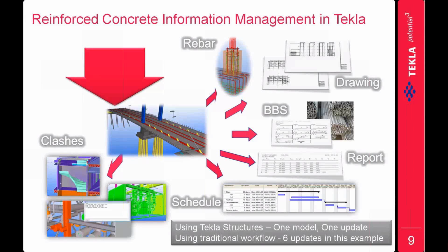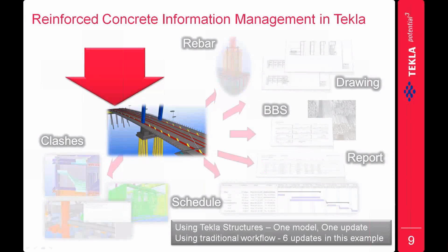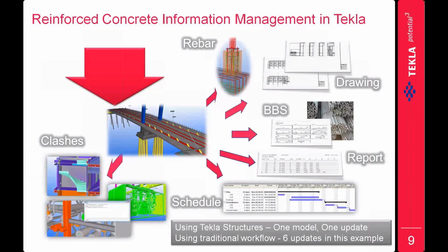So if we change any information in the model, it automatically updates instantly in all the areas, like in rebars, in drawing, in bar bending schedule, even in reports, and even with the clashes with the third-party reference model, it automatically updates. Whereas in the 2D based workflow, we need to ask each and every one to come with the revisions. But in this workflow, it updates instantly. If you see the traditional workflow, where 6 updates are required, but here in Tekla Structures, it's one single model and one single update.